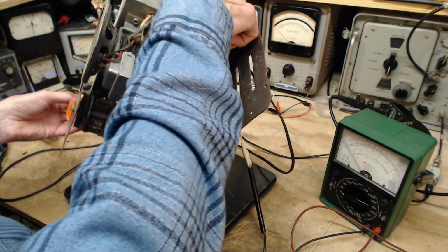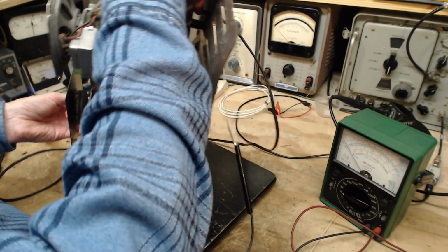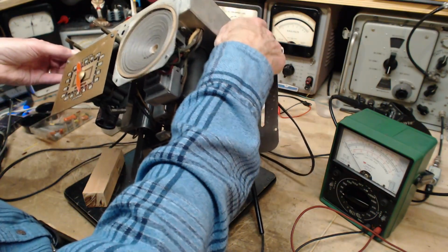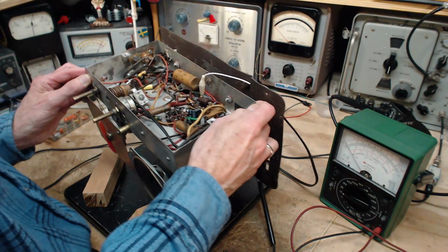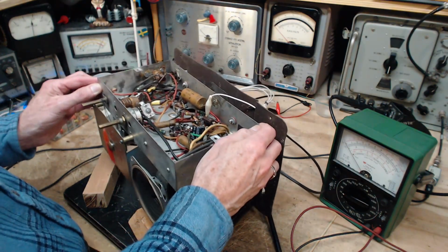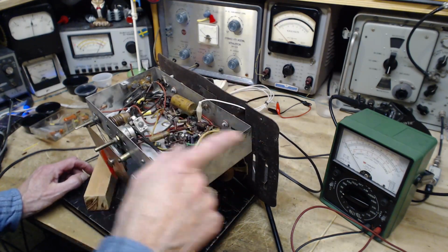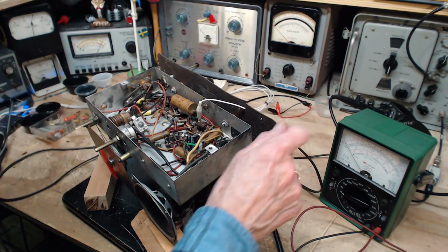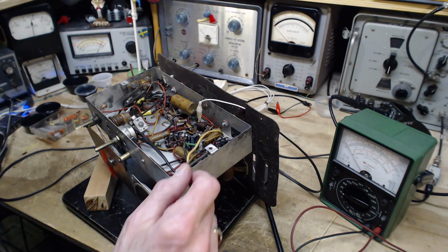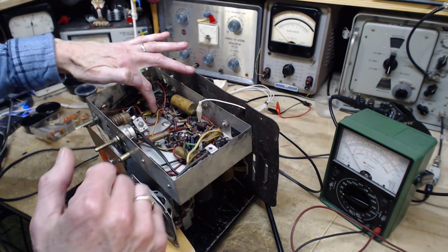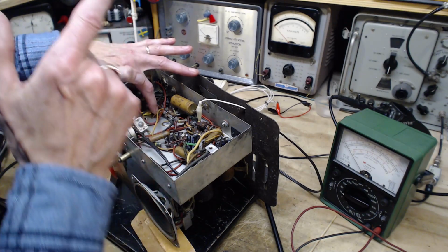So yeah, you know what? It's going, no, it's going to the antenna. That's right. It goes to the antenna because it goes through the antenna winding to get to the first grid. So this yellow one here, the power's off now, this yellow one is going to tube number 1.